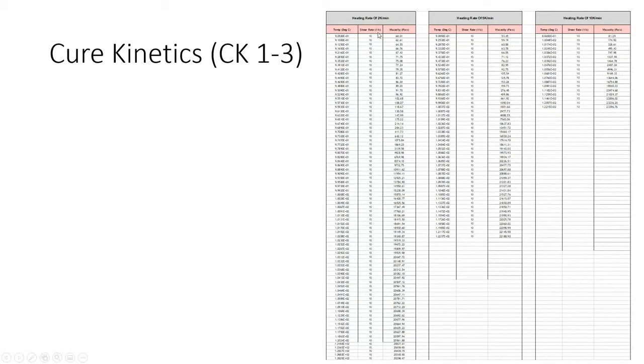But when the temperature rate is slower, of course, we see a lot more data. So it's always important to have a temperature rate that measures well. In some cases we might do 1K per minute, or sometimes we have to go to 20K per minute. This rate worked out very well for this particular cure speed for this particular material, which is a platinum cured LSR silicone. But if you're using perhaps a tire material, you might need to increase the rate because the cure system would be much slower. So the rates are adjustable, is what I'm saying.